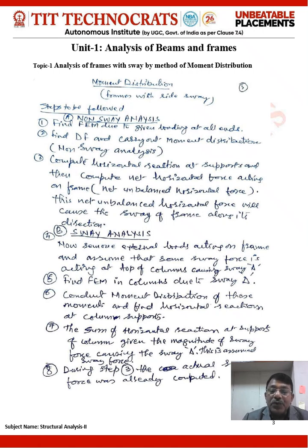Now we are going to understand how to proceed for the frames which have unsymmetry of loading or unsymmetry in the geometry, causing the sway of the frame when the loads are being applied. The frames which have this kind of nature, when analyzed by the method of moment distribution, we need to follow certain steps. The entire frame would be analyzed using two important steps.